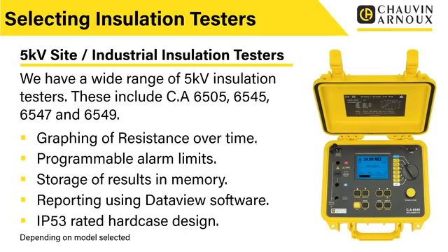Now, we can also set programmable alarm limits. So if the insulation is below a certain value, it will let you know. It'll give you a warning, so you don't have to look at it specifically and read. You can set up the alarm. So if you're carrying out a lot of tests, maybe on motor windings, you can set the alarm, listen out for it, and it will tell you, rather than you having to keep an eye on the screen all the time.